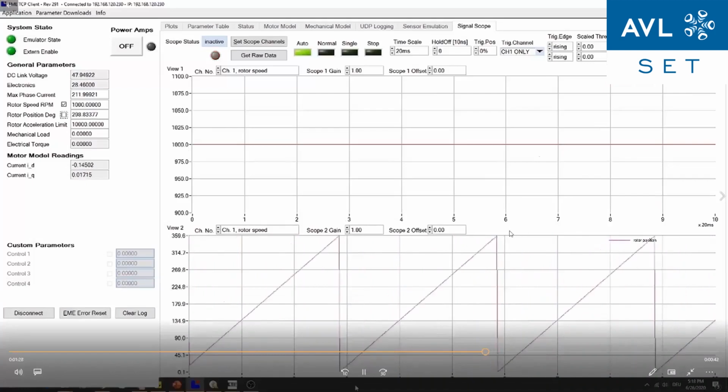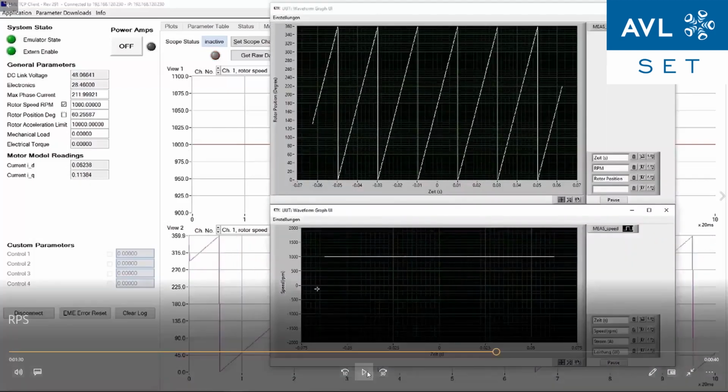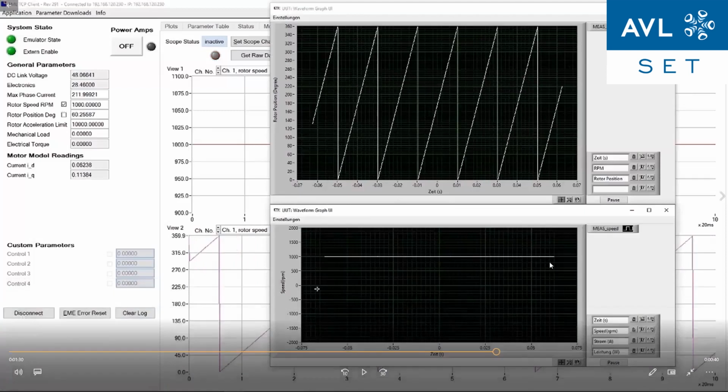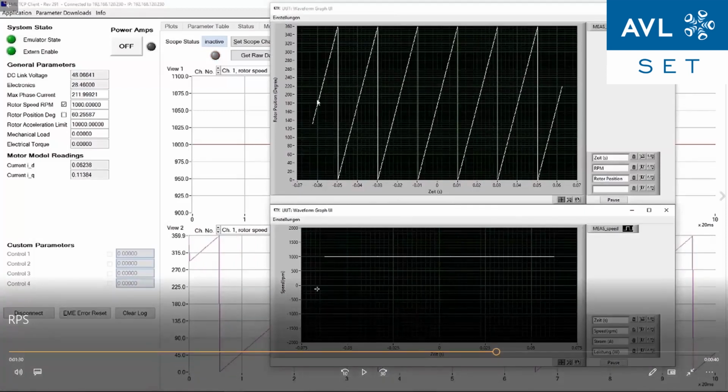the scope window here. And then we need to confirm that the same signals, the speed value and the direction, are also reflected on the inverter side, whether the inverter is also reading this value or not. This is one of the key factors which we need to verify beforehand. We can also see the graphical user interface for the said inverter, where I have plotted the speed and the rotor position. This is also reading the correct position and correct speed with the correct magnitude and direction.